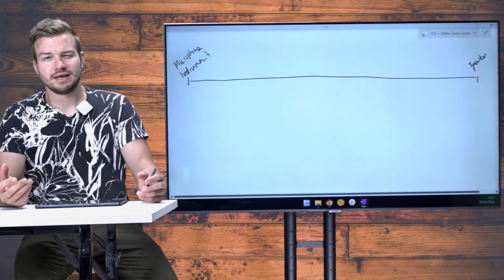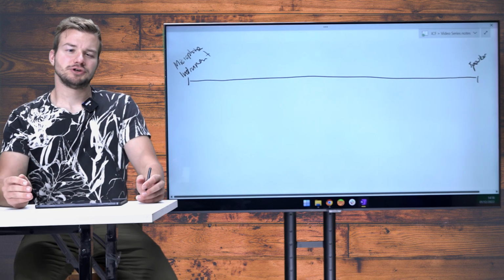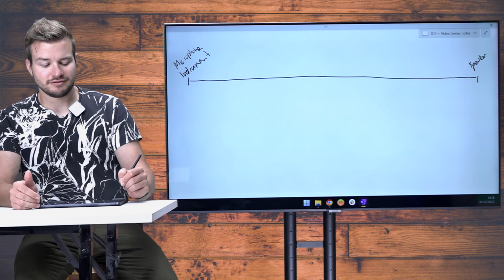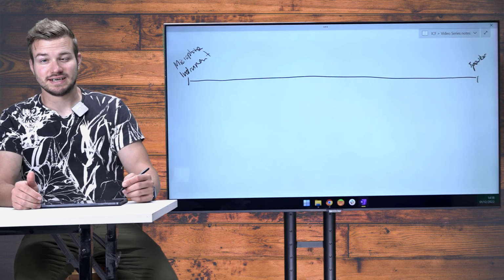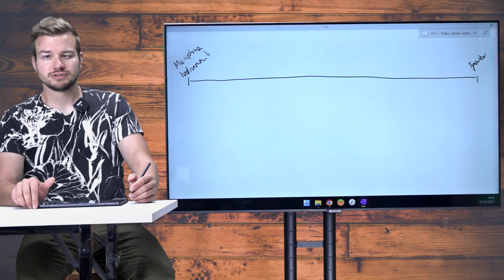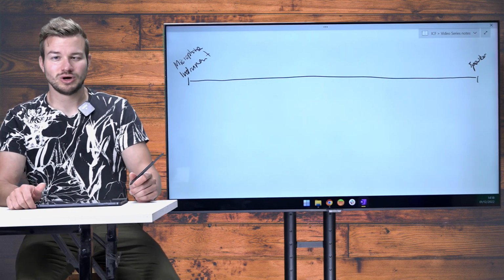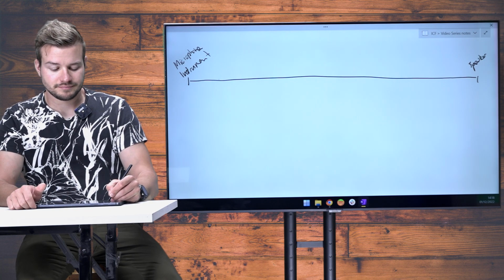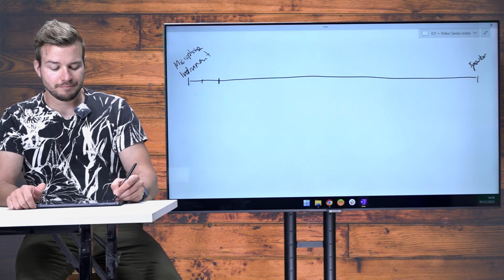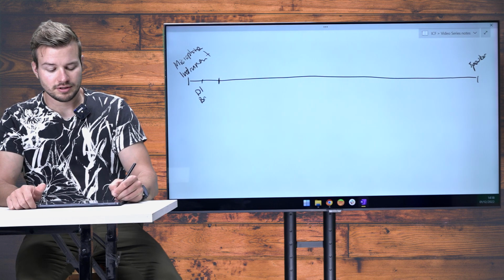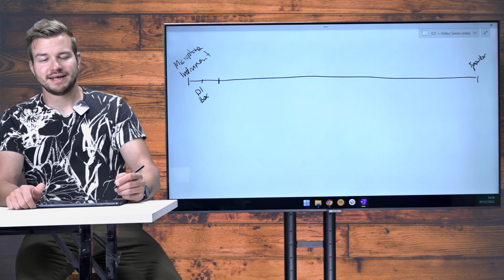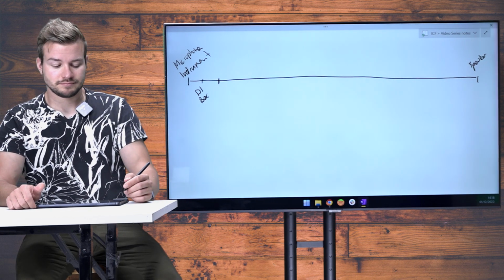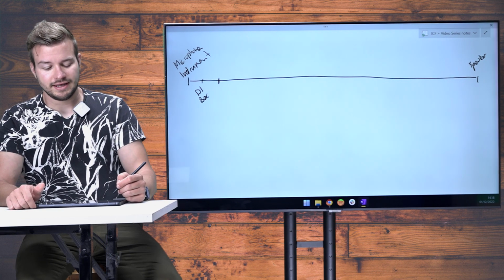And there are literally a lot of places where there are gains, where you can change the volume of the signal. The first one is at the microphone or at the instrument itself. Most of the instruments and some microphones do have gains. So that's the first point where you have a gain. Then the next one could be the DI box. Most DI boxes do have a pad. You can either raise or lower the signal by 20 dB. So there is often a gain too.